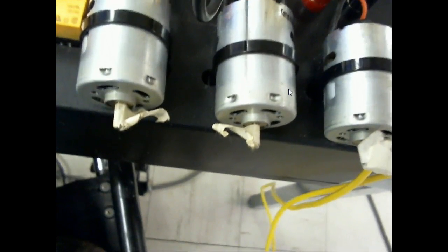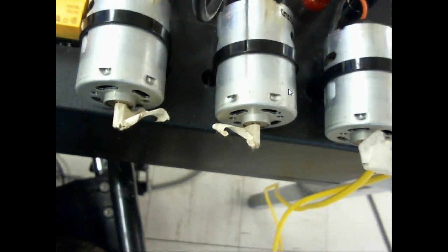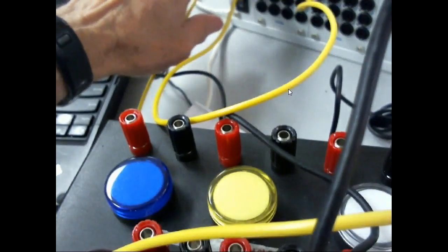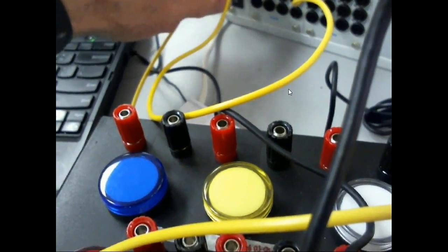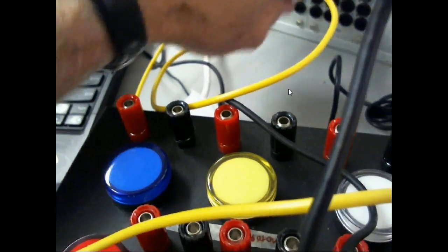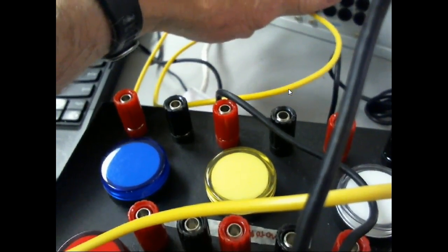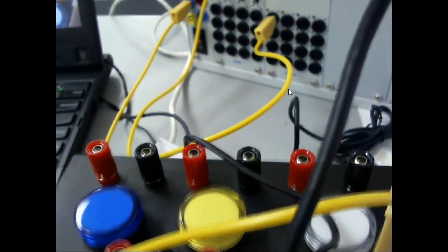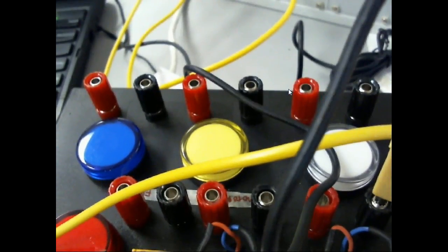So what I would do is run a common between what? All my output devices themselves. And then I run the common out from my minus common, because my outputs are set up to do what? Source. So I'm going to set the devices that I hook up to my ports to sink, right? Everybody okay there? So the motor should come in and run.